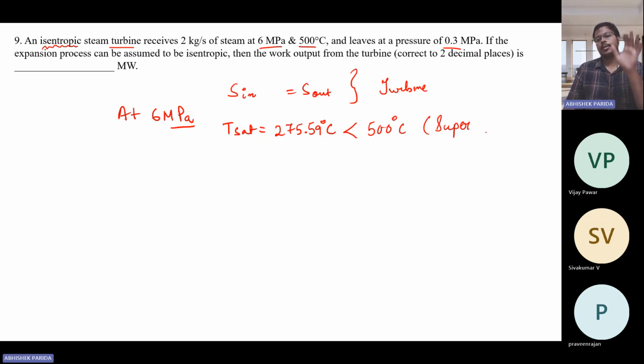And mostly always, when we study the power plant, we'll get to know that the turbine's inlet will mostly be in a dry state, that is, in a superheated state, so that after expansion, it should be close to the saturated vapor line. If there is any presence of water vapor, there might be corrosion. We will see this in the Rankine cycle. We'll surely go through that.